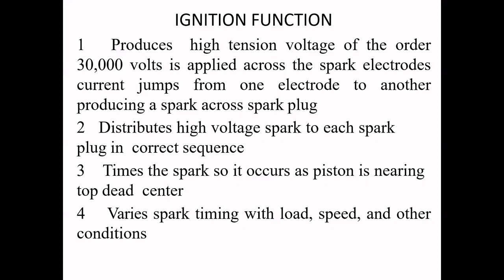Here again I will repeat, the spark gap and its length play an important role, and the temperature of the spark plays an important role for better ignition in the engine. Generally the spark gap length should be 0.9 millimeter to 1.6 millimeters. If it is above 1.6 millimeter or below 0.9 millimeter, the gap will produce poorer ignition in the engine cylinder.